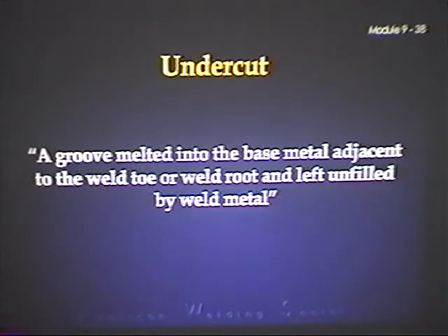Okay. So you're welding two pieces of plate together, and they're part of a wall, and you're making that weld in there. Well, they're held rigidly in place. We're talking about plate welding right now. So there's no give. Well, if you're welding in there, the shrinkage forces of welding are going to cause that to draw in. And if those plates were allowed to give and distort, that would help to eliminate that restraint cracking. If they aren't, those stresses are going to be built up in there. You've got to relieve those stresses someplace, somehow, or else it's going to continue to crack.